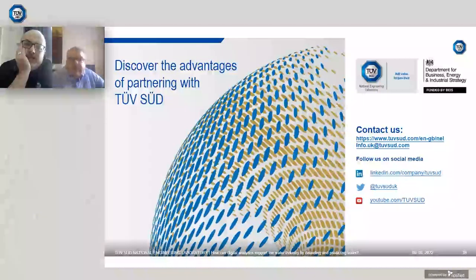Yeah, well, that's some of the problems that I was in Saudi Arabia earlier this year, and that's some of the problems that they're facing. They have meters up to 2.7 meters in diameter, and there are maybe one or two facilities around the world where you could potentially calibrate that, and it would be hugely expensive. But if it's a modern flow meter that produces diagnostic data, we could look at that diagnostic data to see if there's any way of predicting, as we did with the Coriolis and the ultrasonic flow meters, what faults are actually occurring upstream of the meter. So that is a possibility, and that is something that basically the condition-based monitoring tools that I discussed here would be looking at.